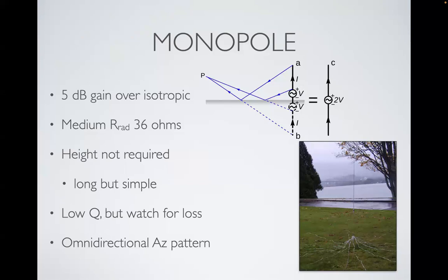So if you have one of these antennas and you like using them, I start with 16 radials and go up from there to about 39 or something like that. After that, it's diminishing returns, but you'd be amazed how well an antenna like this performs if you have more radials. And if you raise the coil up, that really helps too. When I have an antenna like this, the first thing I do is buy more lower sections and push that coil up into the air. That gets more of the current, the radiating part of the antenna, available for you.